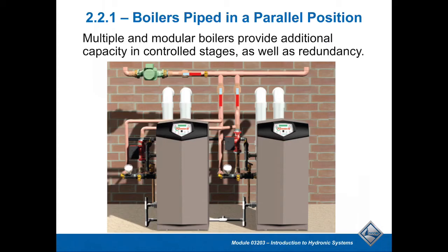So generally, the higher temp polypropylene is the way to go on any type of condensing boiler, unless you have the ability to manage the temperature and minimize the potential of it getting into, let's call it, a non-condensing range in excess of 140 degrees. That would put you at water temps like 140 to 145 or higher.